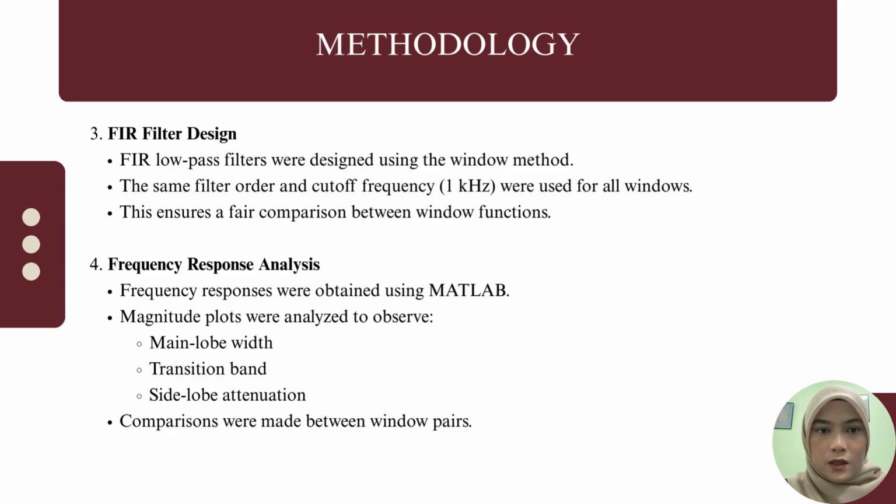Number 3 is FIR filter design. FIR low-pass filters were designed using the window method. The same filter order and cut-off frequency, 1 kHz, were used for all windows. They ensure a fair comparison between window functions.